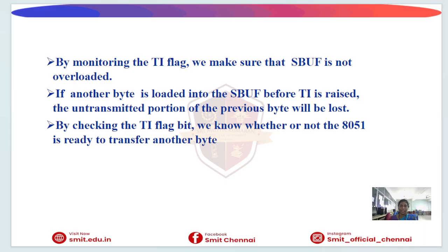By monitoring the TI flag, we can ensure proper synchronization between successive transmissions and avoid overloading the SBUF register. If we send the next character to the SBUF register too early, the SBUF register becomes overloaded.